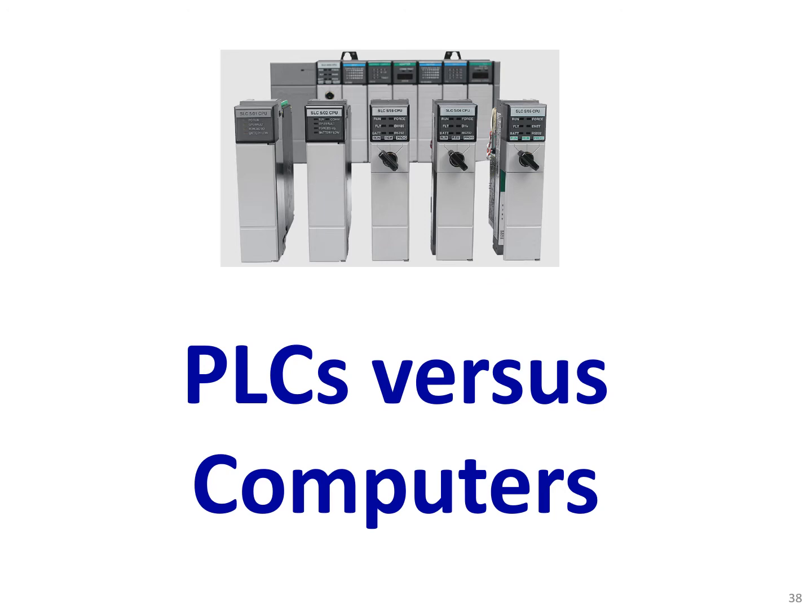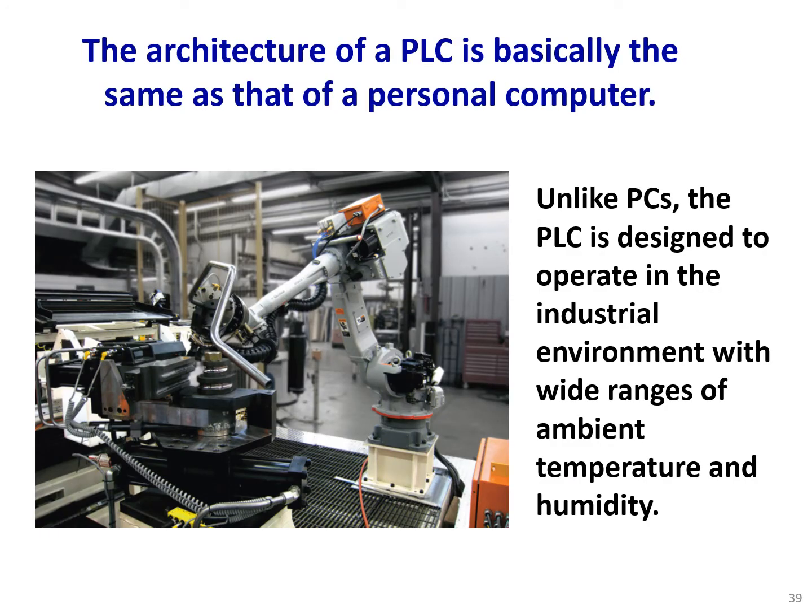PLCs versus computers. The architecture of a PLC is basically the same as that of a personal computer. Unlike PCs, a PLC is designed to operate in the industrial environment with wide ranges of ambient temperature and humidity. So we could have high humidity, dusty environment, high vibration, but still those PLCs will operate on time, do the scanning, read the inputs, and update outputs.